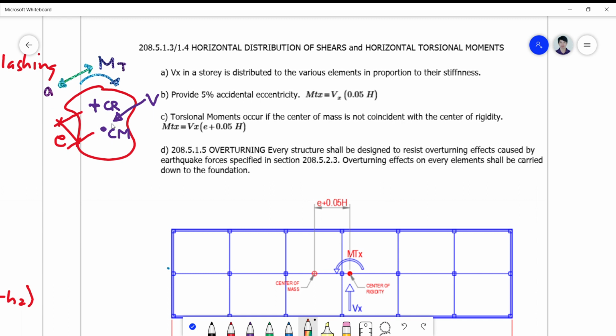This is your acceleration, which is going back and forth. In this regard, this effect of torsion will serve as basis for the distribution of your forces unevenly. It's not an equal distribution on points where the stiffness is placed. Let's say my stiffness is distributed somewhere: here I have a column, there I have a column, here I have another column. The forces induced will no longer be equivalent to each other.